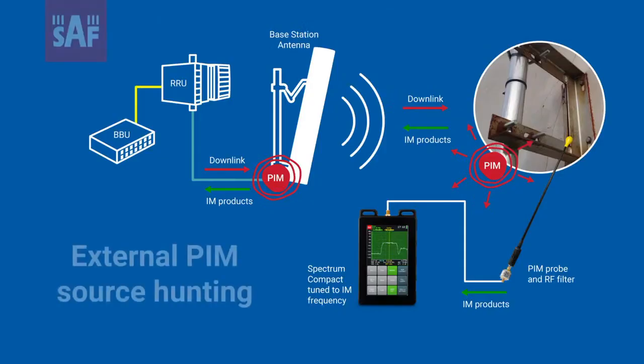We're not one of them, unfortunately, but using those products, once you've established where the problems exist, you can simply correct them. It could be a bad connector, and you need to replace it. It could be a dirty connector, and you need to clean it. It could be that you didn't torque the connector down to the specification required. Simple things like that will make internal PIM a headache for the mobile operator.